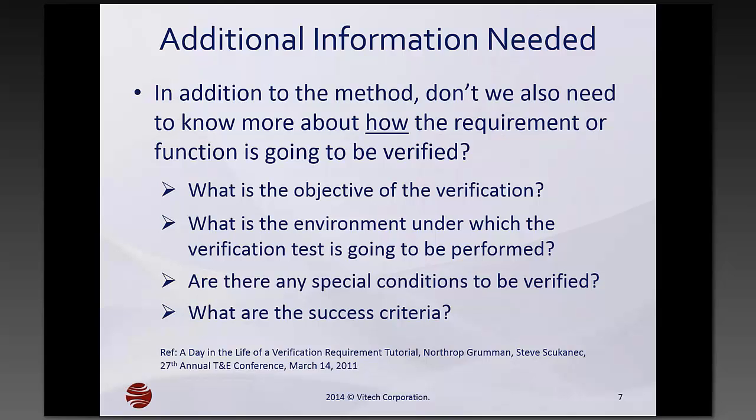What they didn't do during the test is they didn't test it at 800, they didn't test it at 1,200. And they also found out that when they closed 2 or 3 valves in close sequence, they didn't have enough pressure in the accumulator to close the valves within the time frame. So if they had written their verification requirement to say, we're going to test the ability to close the valves